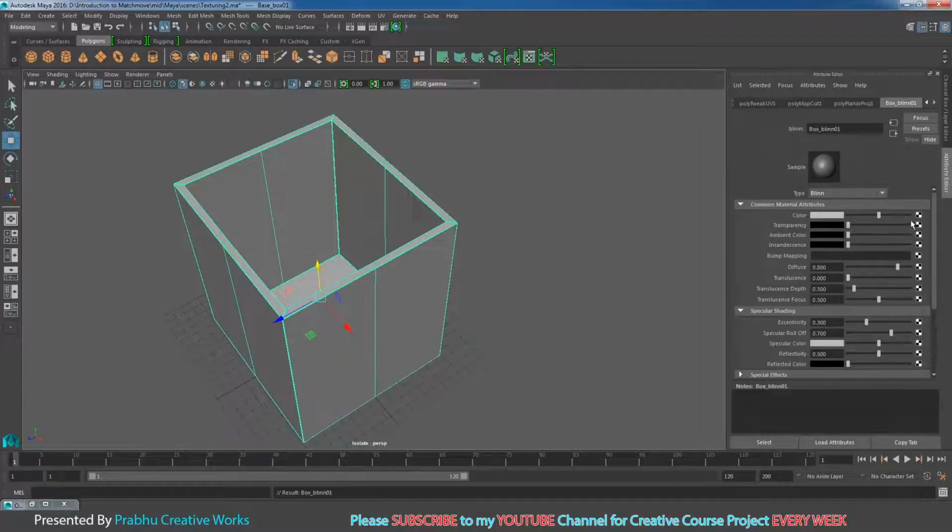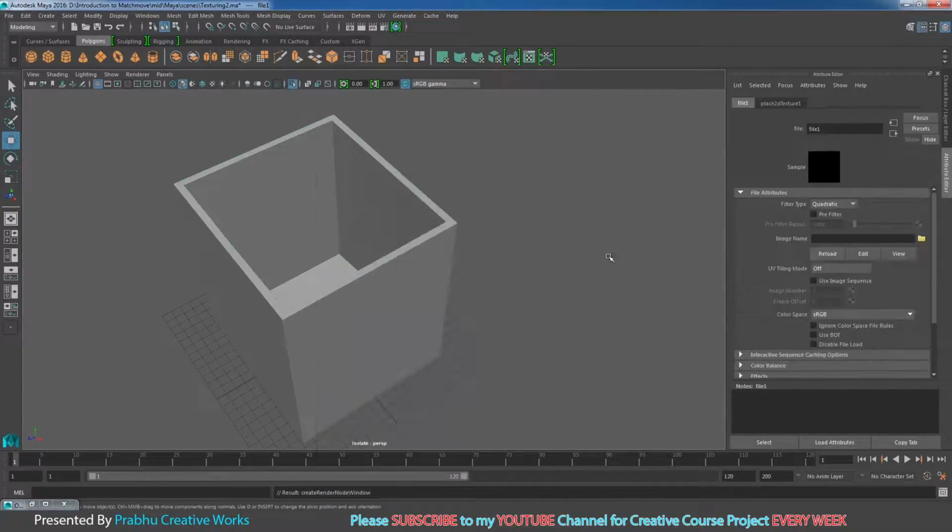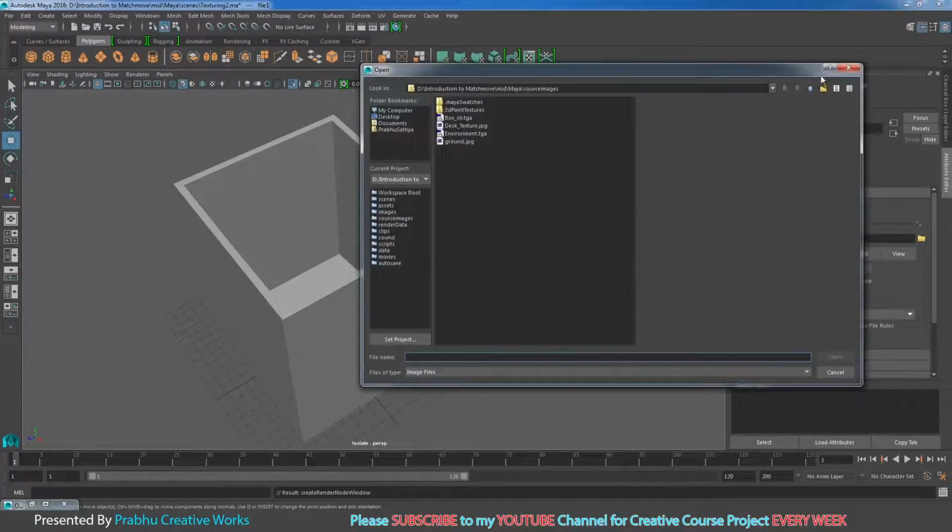So now click on this checker one. So color checker and choose file. So choose filter type to off. So if you have quadratic, your texture should be blur in render. So I didn't want any blur for our texture. So I want to change my filter type to off and choose my image name.